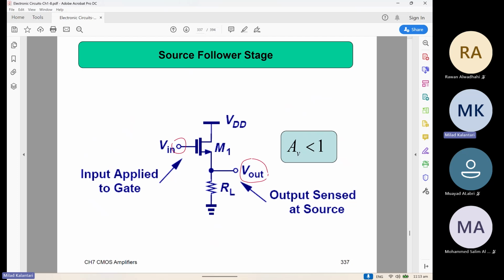But on the other hand, we still need the output impedance to be lower for voltage amplifiers. So if you use this kind of common collector or common drain for the MOSFET, then the output impedance will be low because what you are seeing from the source is low, right? It is a 1 over GM impedance.